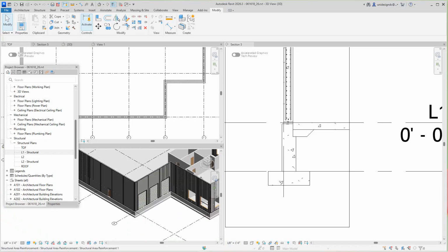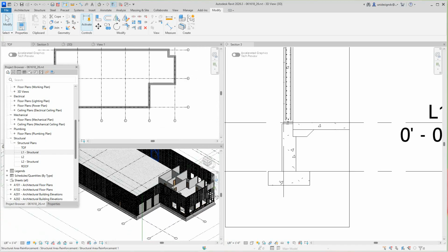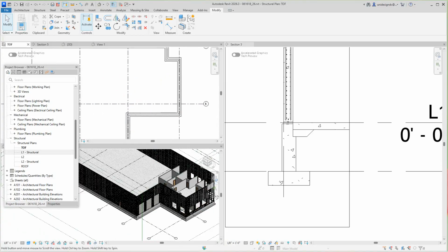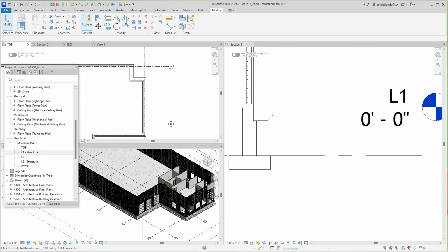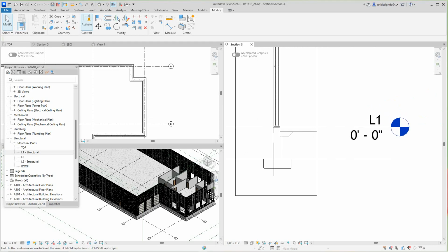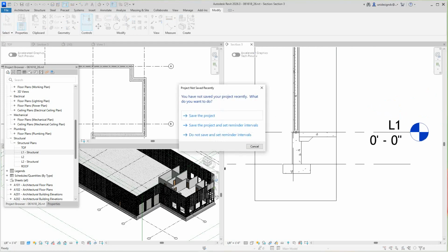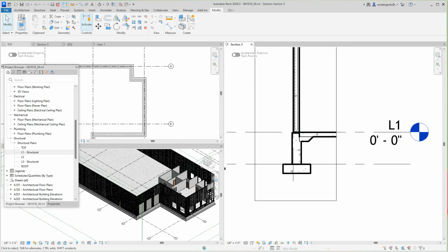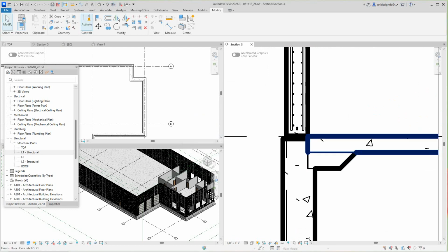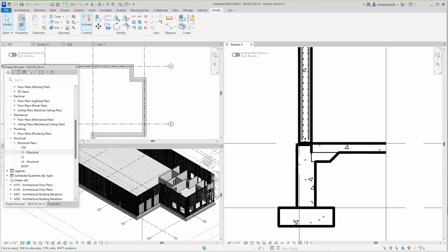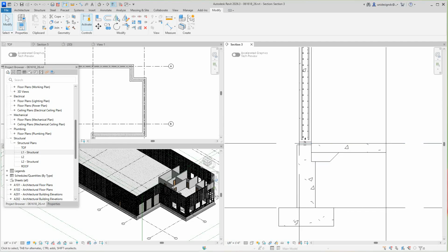I went on and finished the wall panels in this view. And here we've got our top of footing level where we're going to put in our columns. In this view, we did get our slab edge in. And what I'm going to do, I'm going to put this in a thicker view. Let's see if we can find a thin view so we can kind of see what's going on. What I want to do here, I want to join this geometry.